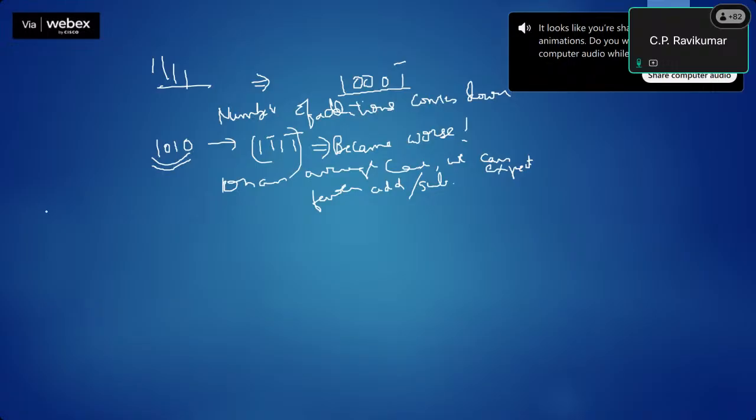So let us multiply 5 and maybe 6. We'll load the accumulator with 0, and this guy is 0, 1, 1, 0 and 0, 1, 0, 1. So I've taken this as a multiplicand and this as a multiplier. We'll create one extra bit here which is initialized to 0. We'll compare these two. If it is 0, 0, we simply shift.